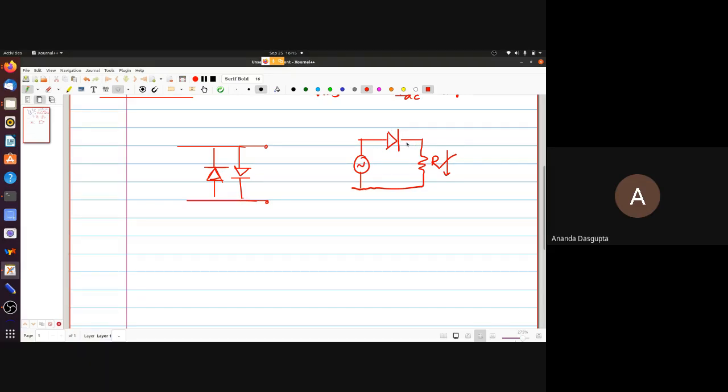Now, if you have a non-ideal diode, you can approximate it by the effective circuit that we talked about: an ideal diode D, a V gamma cut-in voltage, and a small resistance which for most purposes can be ignored. V gamma also can be ignored provided your voltages are big, but V gamma typically is of the order of 0.7 volts to 1 volt depending on the kind of diode. For pulse shaping, you usually use small signals, small voltages, and there 0.7 volts can be substantial. You cannot really ignore it.